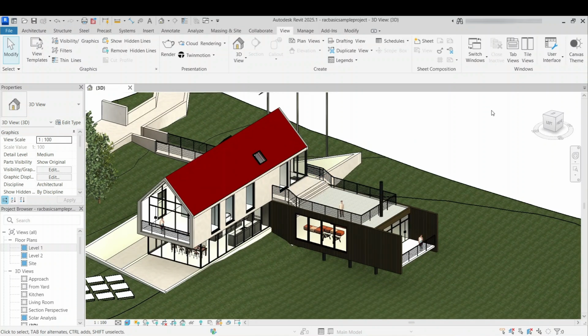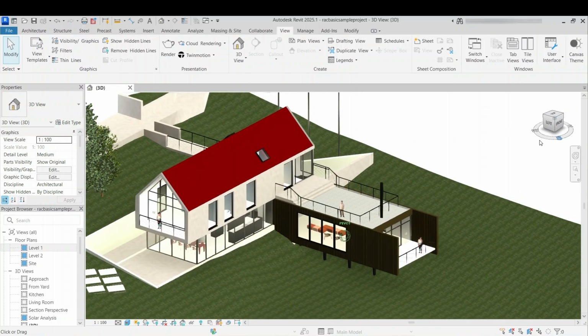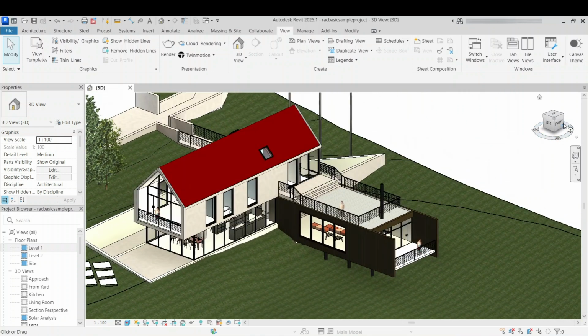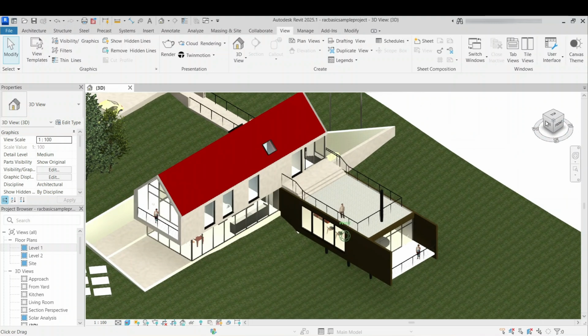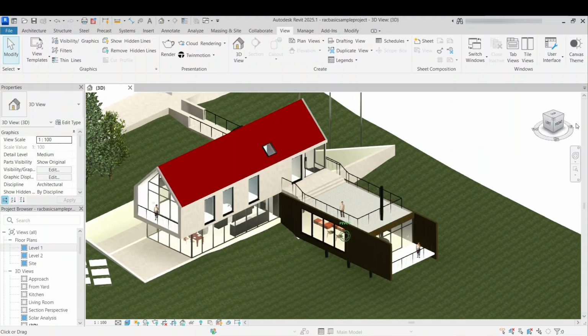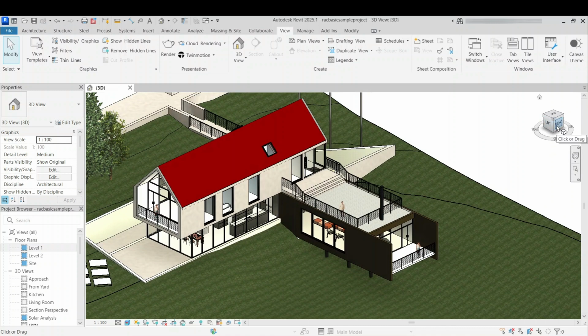You can also use the view cube for orbiting. Click and drag the circular disc at the bottom of the cube to rotate the model around axis. If we talk about the cube, clicking and dragging anywhere on it lets you orbit freely, just like the shift and the wheel method. The view cube can also quickly orient you to preset views like front, right and top.